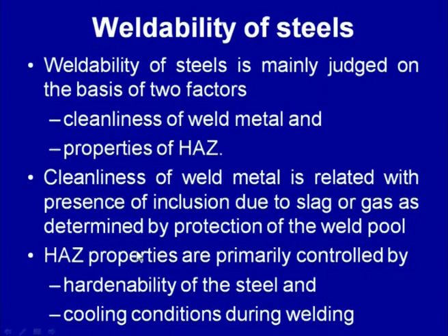The inactive gases are generated by thermal decomposition of the fluxes, which are used for protecting the weld pool from the atmospheric contamination of atmospheric gases. So, this is about the cleanliness aspect.